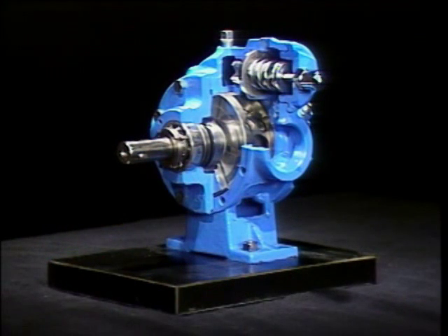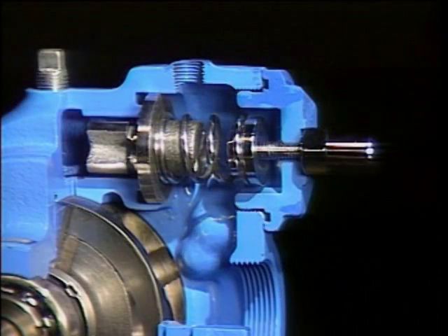Like all positive displacement pumps, a rotary pump will deliver a controlled amount of liquid to its discharge during normal operation. But if the discharge is blocked, the liquid won't have any place to go. If this happens, pressure could build up and damage or destroy the driver, the pump, or other equipment. To prevent this, most positive displacement pumps, like this one, have some type of protective device to guard against excessive pressure. A common protective device used for this is a relief valve.